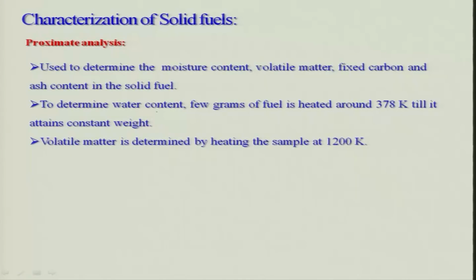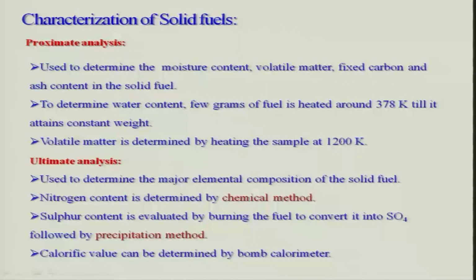And we need to determine water content. A few grams of fuel is heated to around 378 Kelvin till it attains constant weight. This is generally the standard procedure used to analyze this. And volatile matter can be determined if the sample is heated at 1200 Kelvin for a certain period of time. So these are to be done so that you can then find out the ultimate analysis.